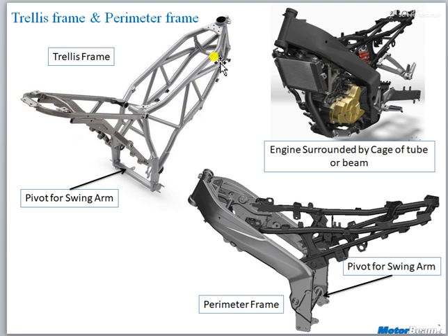By adding the main tube and down tube together through some short bars, we get two big members going downward from the head tube. One member goes from one side, another from the other side, coming from the head tube and going towards the backbone area. At the bottom it provides a pivot, and on that pivot a swing arm is located, which is a part of the suspension system.